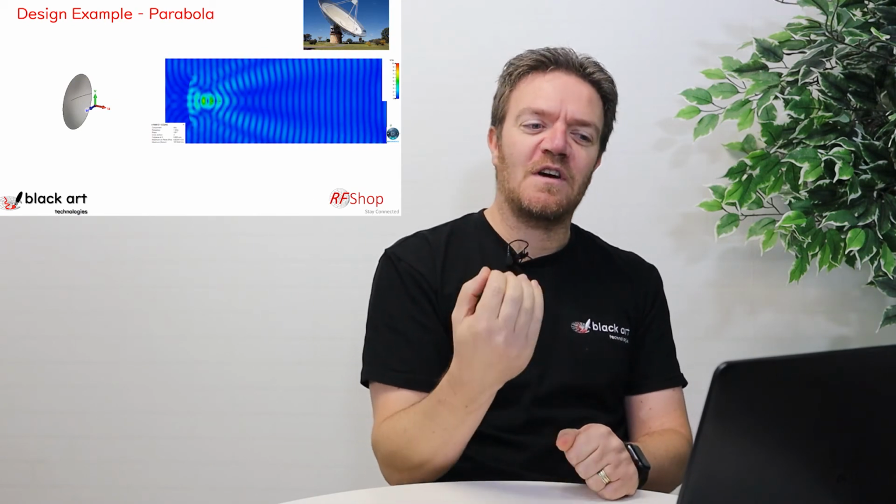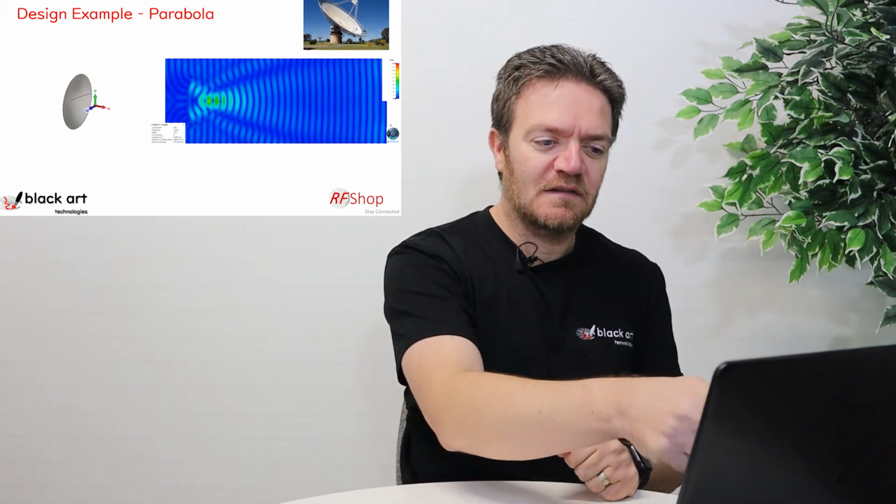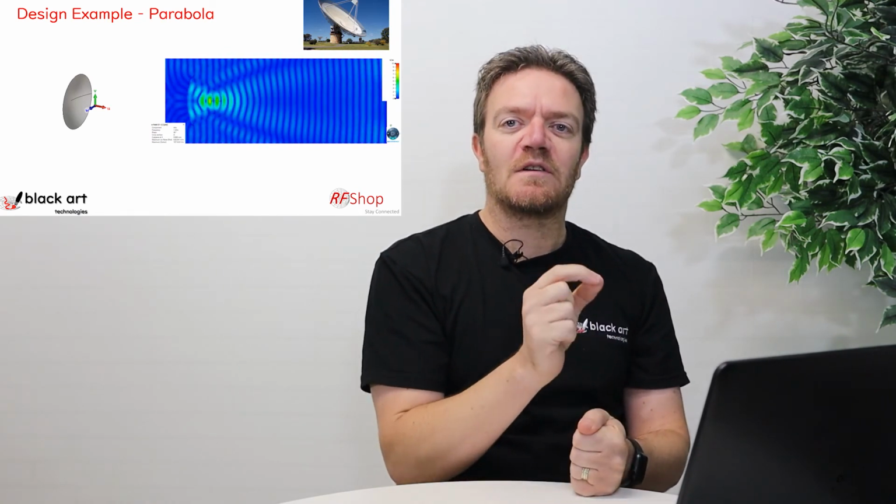The focal point shows you that is the place where you want to put another antenna, and that antenna is going to pick up that green level of E field. So in other words, much stronger signal. So the focal point is where you would want your parabolic dish to have its antenna of some sort.